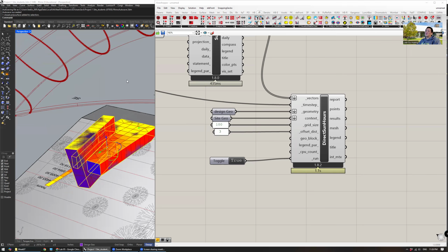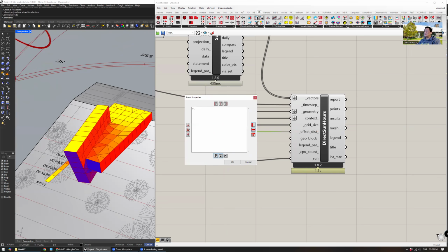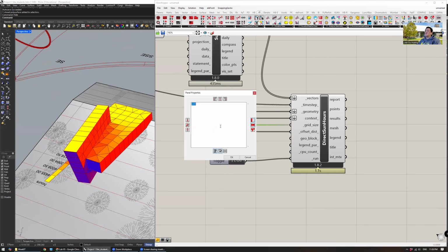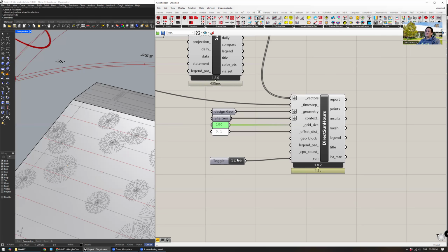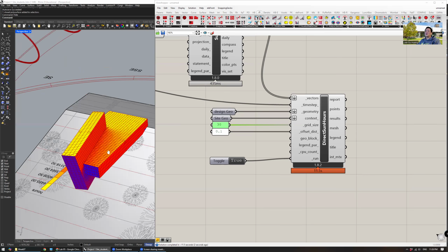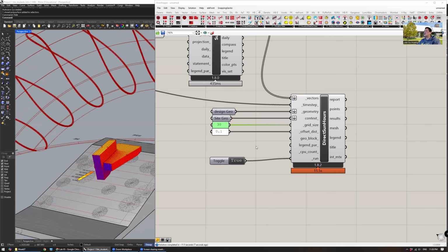But usually, again, I just find it easier to hide the design geometry in the Rhino file and not have to mess with this too much, right? So revert that back to 0.1. And so this actually can probably be 30, at least for this unit's size and scale and size of the building. So it will take a little longer to calculate as I'm waiting a couple moments. Okay, so that seems like a reasonable analysis grid scale for a building this size, right?